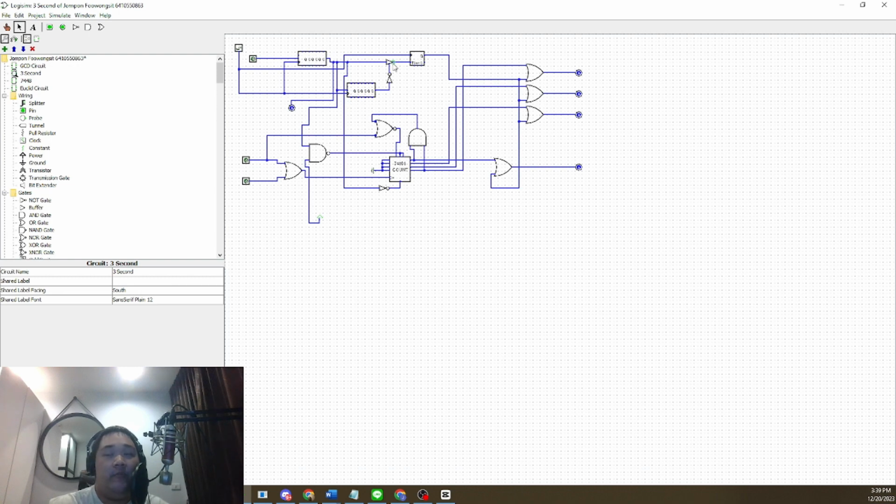Following this, a shift register with 6 states is utilized to create a blink effect here. After we have the shift register, we send it to here, signaling the initiation of the resetting process. Subsequently, the 74161 counter is integrated into the circuit to ensure that the reset circuit here works after the 3 seconds, for added protection against unintentional addition via the reset button.